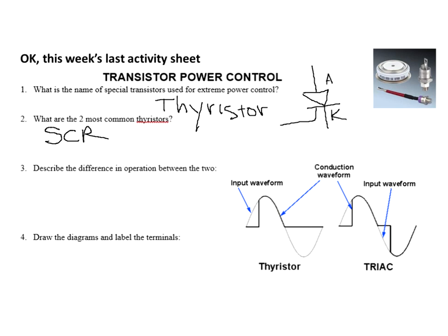Why is it similar? You've got three terminals: one, two, and a controlling terminal. This is where all the current flows, in the anode and the cathode. Of course, it has to be forward biased to work. This terminal over here, the gate, is what controls the current in the anode and cathode. Isn't that what third quarter was all about? Hopefully you got that. You have mostly three-terminal devices, and you're controlling a ton of current in two terminals with a tiny current in the other terminal.